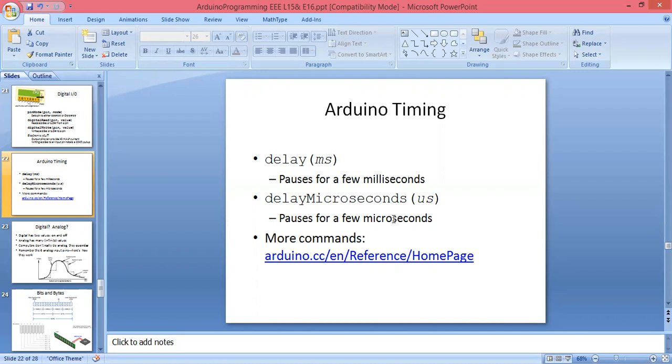If you are giving the delay in the microseconds, what we have to do? We have to convert that value into microseconds. But in your syllabus you are having only small numbers of programs. तुम्हें क्या है? सिर्फ LVDT, LCD, LED, serial communication, LM35, then strain gauge and LVDT. Only 6 to 7 programs. So there is no need of these microseconds. You will need only the delay, which will be measured in the milliseconds. So directly you can use delay instruction and you can write that time in the open and close parentheses.